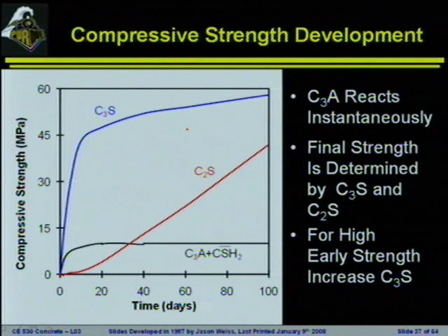As I mentioned before, we weren't making any quality judgments when we were talking about degree of hydration. Now this graph starts to say, well, they may react at different rates, but just because they're reacting doesn't mean they're going to have the same strength. So here what we've done is we've plotted the strength development for each of these materials as a function of time. And a slightly different picture starts to emerge.